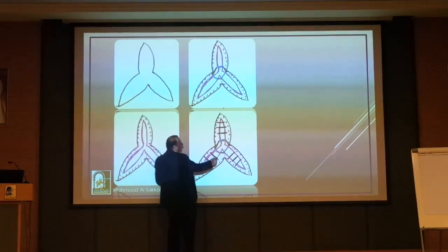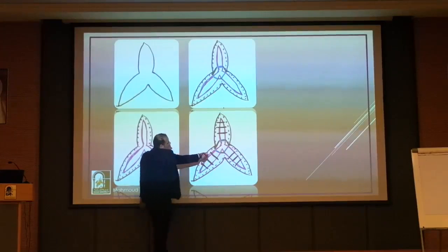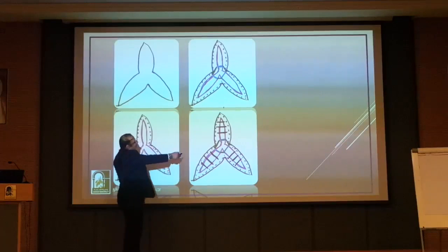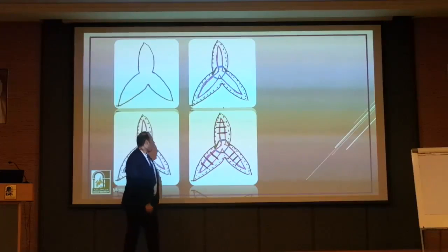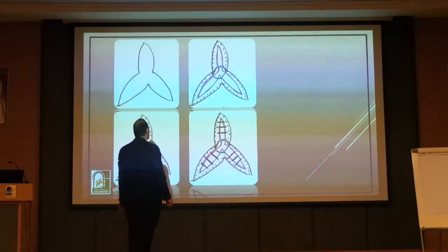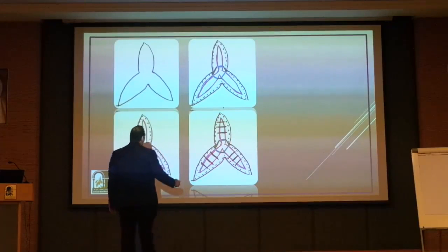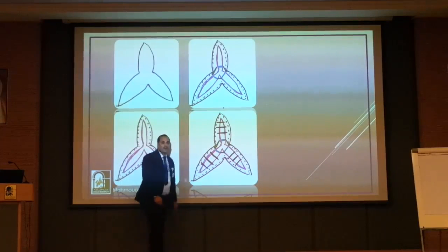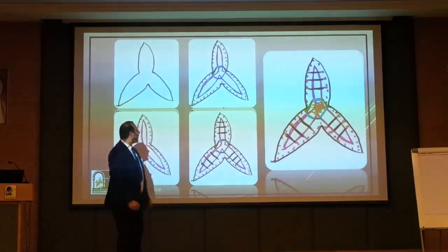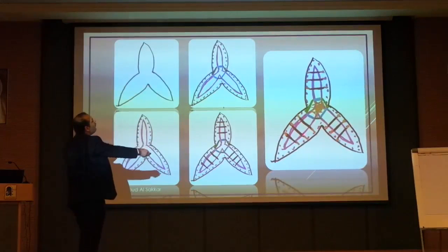Of course, you're going to have some cores here because of services, stairs, lifts, everything, and make some tubes over there, but shear walls. And then what? Then you can make full use of what? Because you already have a tube wall, a core, and columns here, you can make outriggers. Correct? Can I make an outrigger? And that is almost what happened in Burj Khalifa.